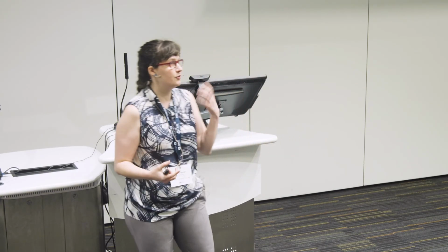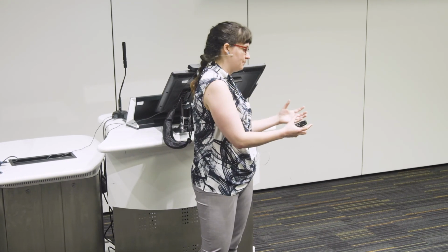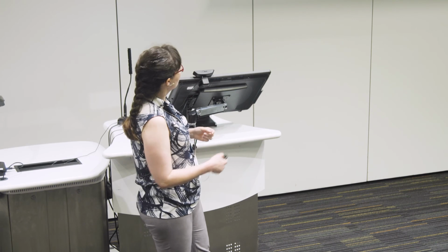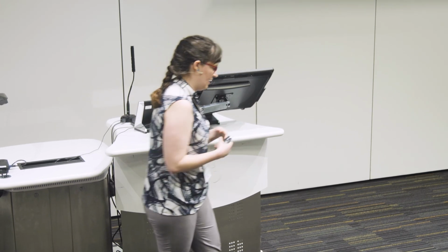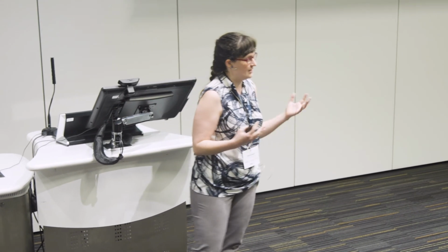Because if you want to crystallize an API, you don't just care about how fast it's going. I mentioned we have to do all these offline experiments for physical form or visual inspection, but we can start bringing these in by maybe adding a Raman probe that was offline, but maybe the robot now reaches into a black box and puts the vial in and says, all right, now collect me a Raman spectra, or collect me an XRPD pattern, or look at this camera. Does this camera use some image analysis to look for agglomeration and fouling? So again, we're going to keep expanding this. We've identified a very quick way of bringing in another crystalline platform. We'll immediately double our output of these experiments.